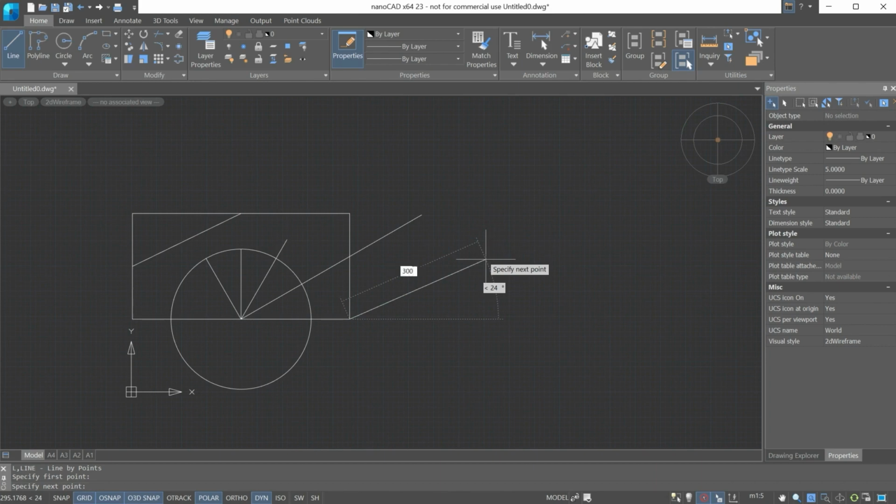You can enter it manually on the keyboard. And accordingly the displacement angle. Let's press Tab. Let's put it 35. You see that it is also highlighted by polar tracking. We won't go into detail about it now. We'll cover it in the next lessons.